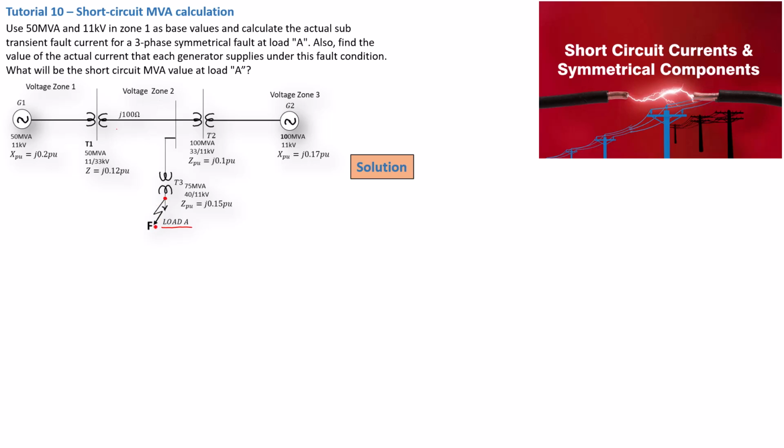Why is it important for us to determine the level of the short circuit here? It is because we want to ensure that we can provide the protection when it happens. If you do not know the level of your short circuit, it will be difficult for you to spec a circuit breaker that can break it and prevent fire or explosions. So a lot of things can go wrong.